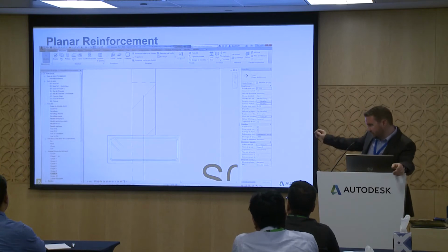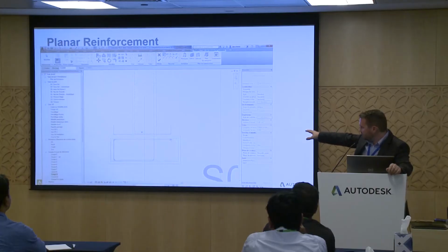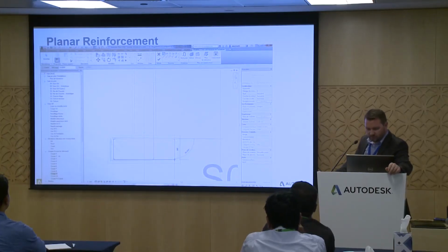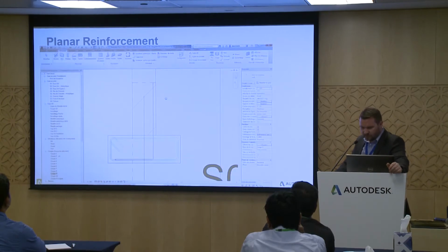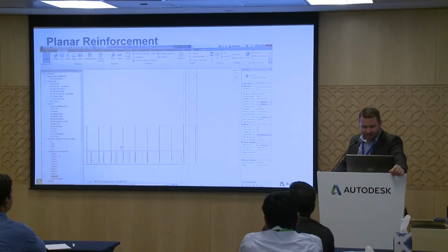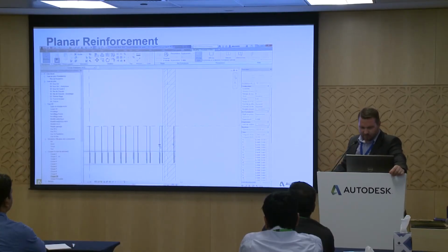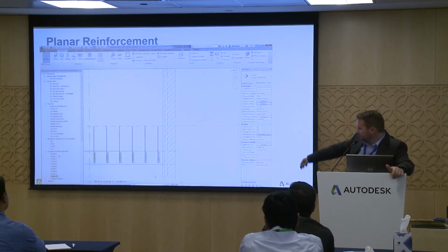And you have grip at the end, so it means that if you ungrip, the last reinforcement is not in. And here, for example, I have soil from this part, so I have to do some reinforcement, which is not standard. Take care to the view, in fact, because here you see I changed the view to view my reinforcement correctly, but it's a classic mistake, we can say. And after, you can adjust, because I want to put them on top of the other.